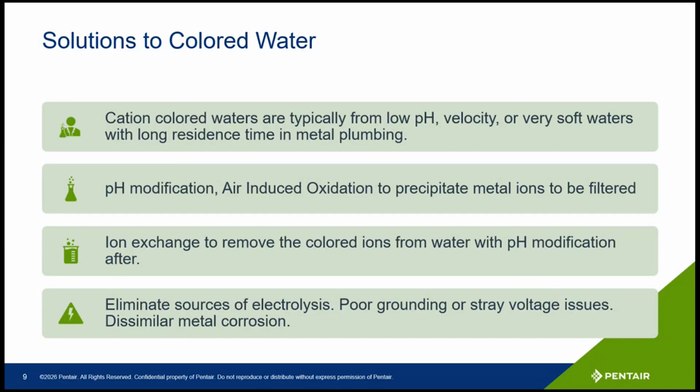So, submicron solutions in waters with colloidal particulate: advanced filtration products such as ultrafiltration may be required. We will see ultrafiltration specified on surface waters to deal with particulate and microbiologicals. You will also see it used on some well systems where you're getting colloidal clay, where it's super sticky and is gumming up the works of everything.